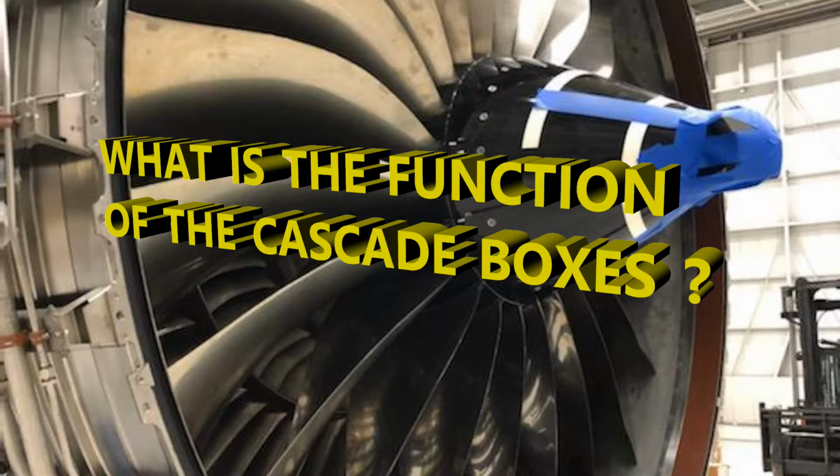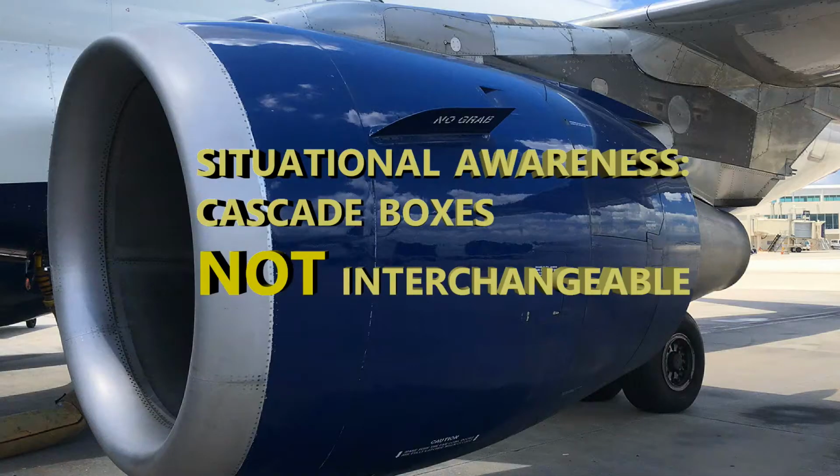Now, things may look alike. I know I've given a great situational awareness here: when you're on the job, a part may look exactly like another part. But if it doesn't have the exact same part numbers for each one, then you've got a different part, and you cannot just substitute one for another. So in this case, with the cascade boxes, they are not interchangeable. So please be careful before you install something, make sure the part number is the correct one.